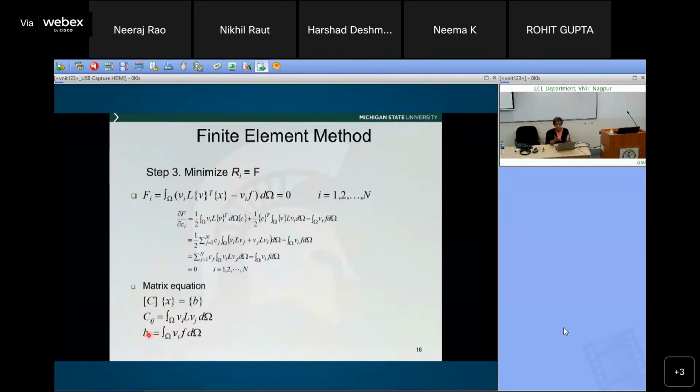But when you use multiple frequencies, you have to keep in mind that at higher frequencies the skin depth is smaller, so my discretization has to be finer. Those are the kind of precautions you have to take. But doing everything in the frequency domain is much easier than doing the time domain. Things like that. Yeah, right. Good.